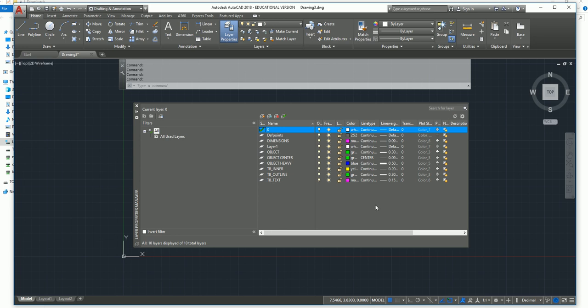You can see in here I've already populated some just so that I can show you guys the style that you could draw with, or naming, structure, all that kind of stuff. Within here you're going to have different information of how you can control your drawing. So right now we're drawing everything on layer 0, and the color's been white, the line type default, the scale or the thickness default. We haven't printed anything, so we haven't really had a reason to do any type of layer adjustment.